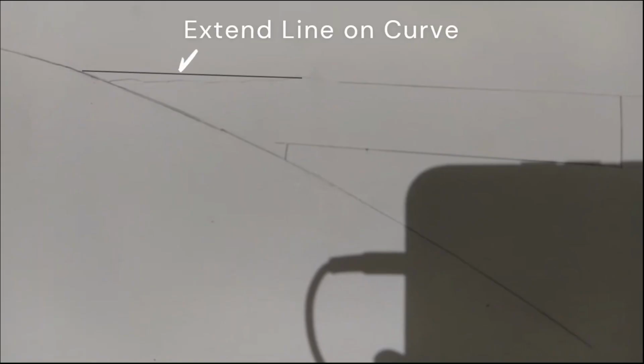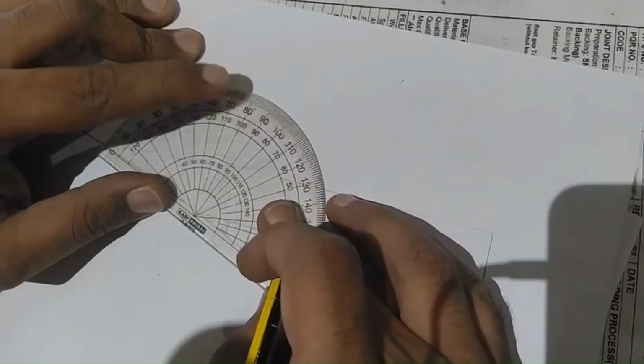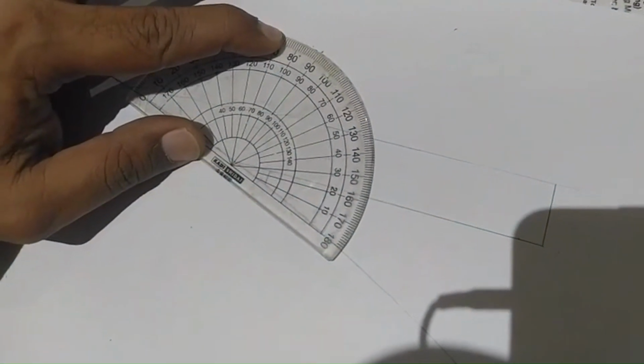Extend the exterior line of the stub thickness until it touches the curve. Note that in accordance with the local dihedral angle definition specified in AWS D1.1, the local dihedral angle is to be measured on the exterior surface. This is the way the profile sketch line is extended.